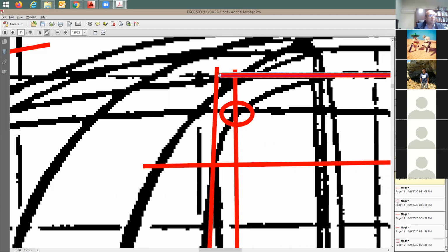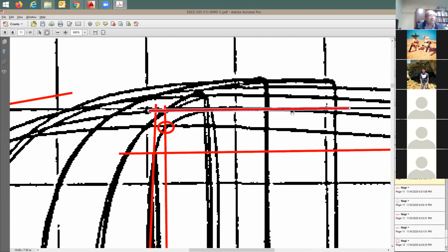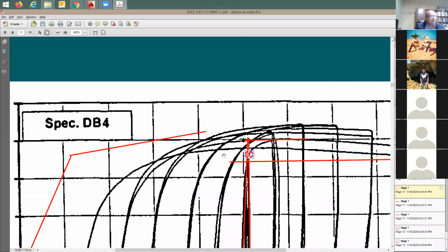And if you like to go more detailed, don't forget that the quality of the background is not really high. So someone can do this. You do a tangent here, and this is gonna be the first tangent, and then we meet. You're gonna say now this is gonna be the yield point, just to be exact. So this is gonna be based on testing. Based on analysis, it's gonna be very simple. We're gonna say this is gonna be the point. Reality is you're gonna have a curve here, right? So you do a tangent, and when they meet, you come here with the vertical line to find the amount of yield displacement.